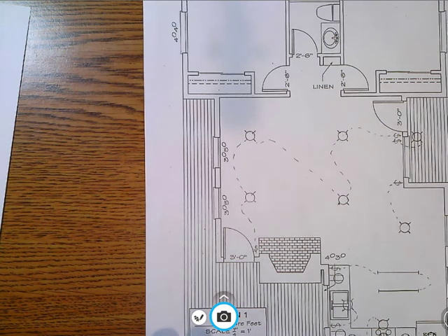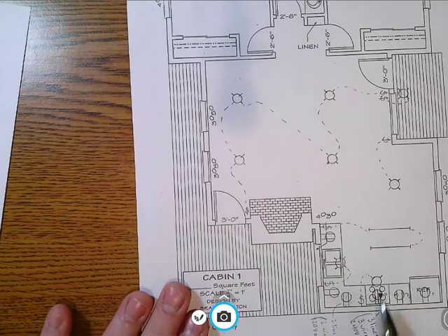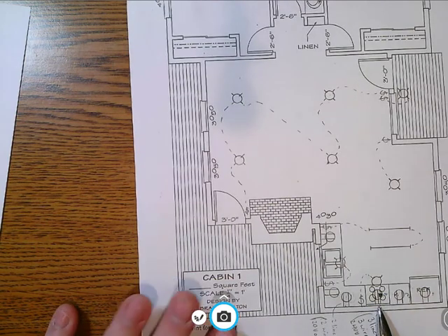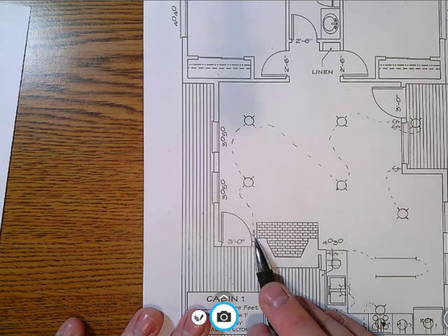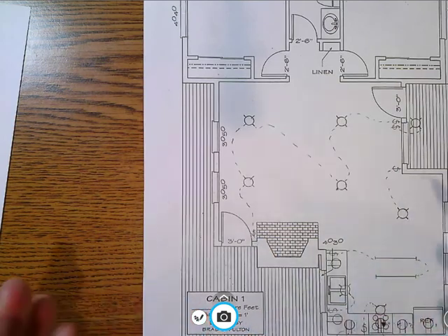How you can bypass this is you can use a 3-wire electrical line, with the 3 wires plus the ground, and install what's referred to as a 3-way switch. With a 3-way switch you only have one hot, and the red wire becomes a second neutral. Sort of like with the stove, where the red wire becomes the second hot, you can use a 3-wire over here and use the 3rd wire as a second neutral.